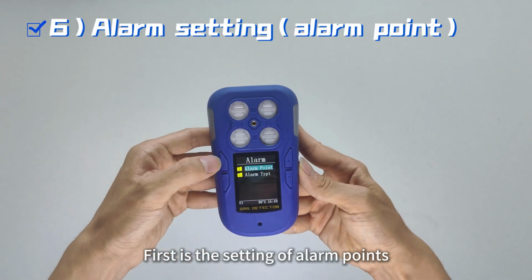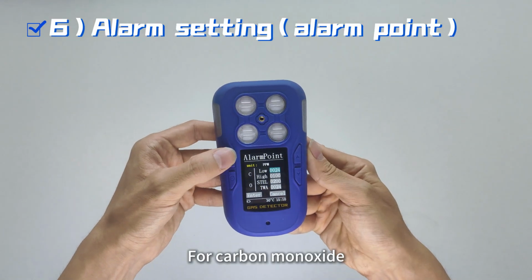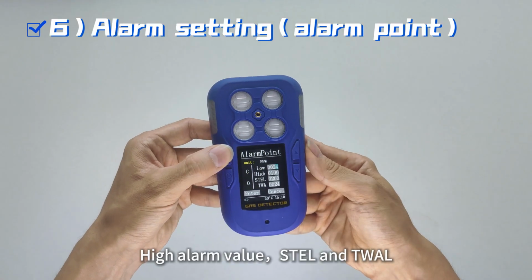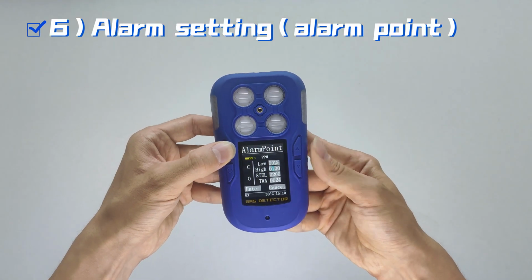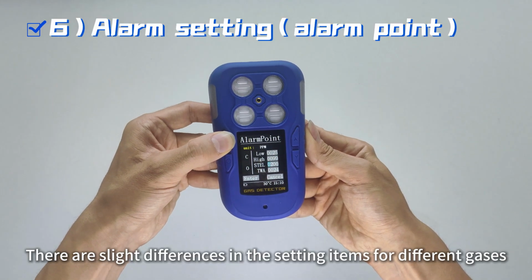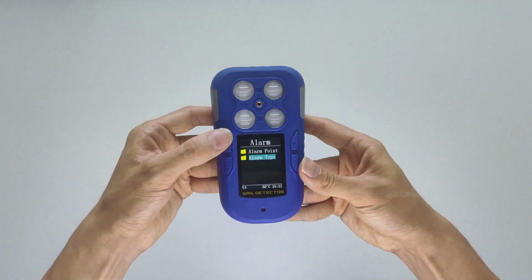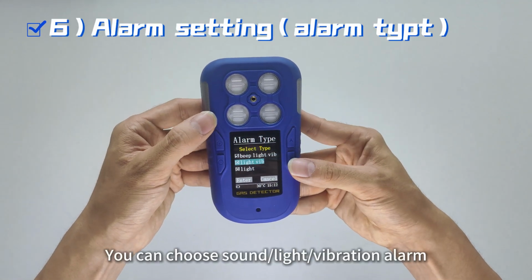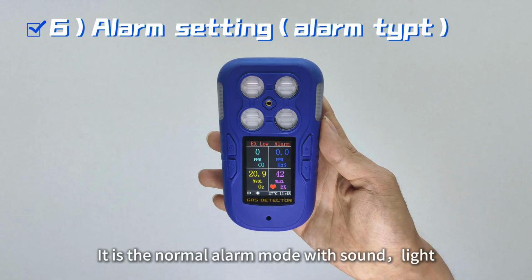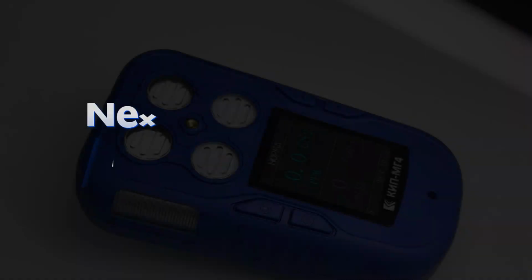First is the setting of alarm points. Enter the corresponding span gas. For carbon monoxide, you can set the low alarm value, high alarm value, STEL, and TWA. There are slight differences in the setting items for different gases. For alarm output, you can choose sound, light, or vibration alarm. At this time, it is the normal alarm mode with sound, light, and vibration all turned on.